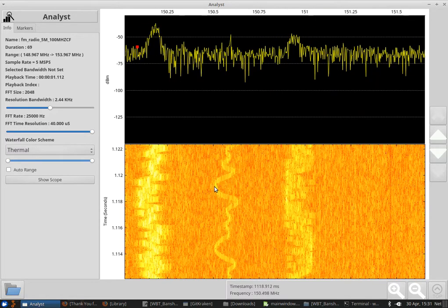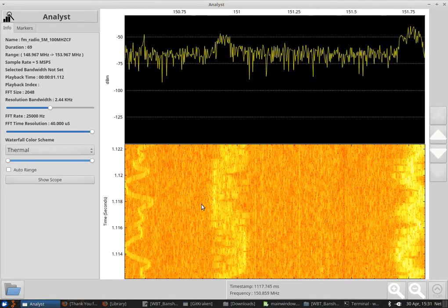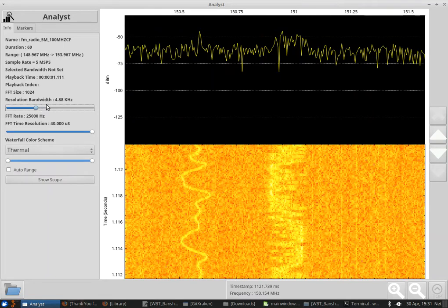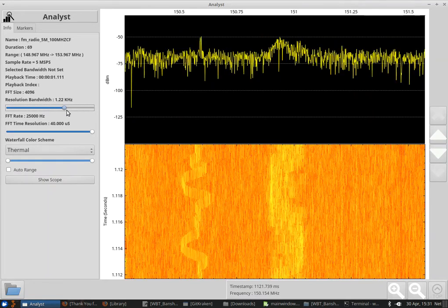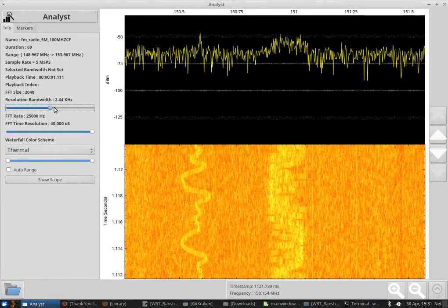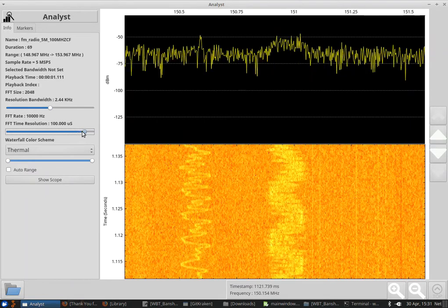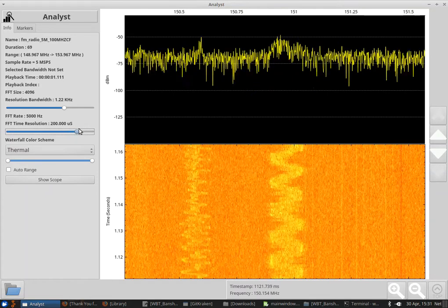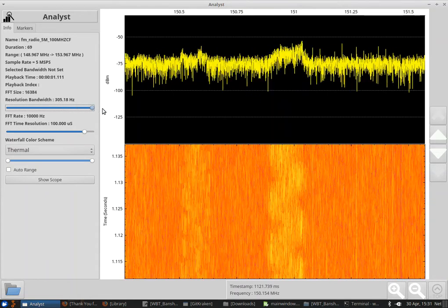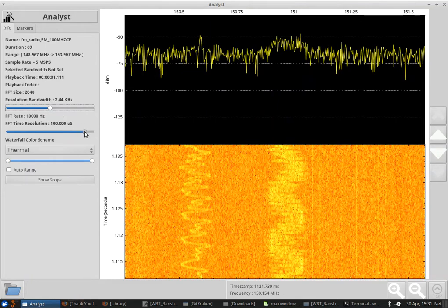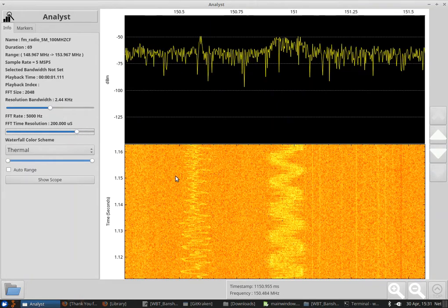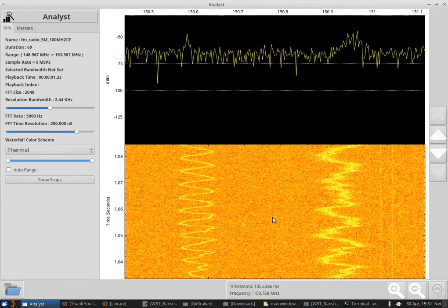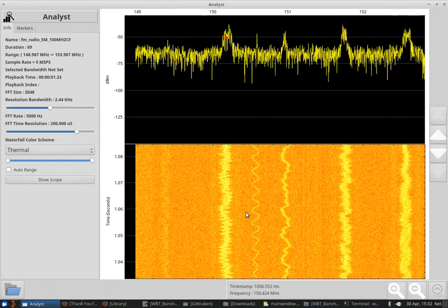With this level of detail, we're starting to take a look at the individual modulations going on inside the waveform. In order to achieve this, Analyst is using overlapped FFTs, and there's only so much data inside the file. So if we hit the point where we're overlapping both in time and frequency, we end up with weird smearing or Moiré patterns. There's definitely a sweet spot that allows you to visualize these things at the maximum native resolution inside the file.